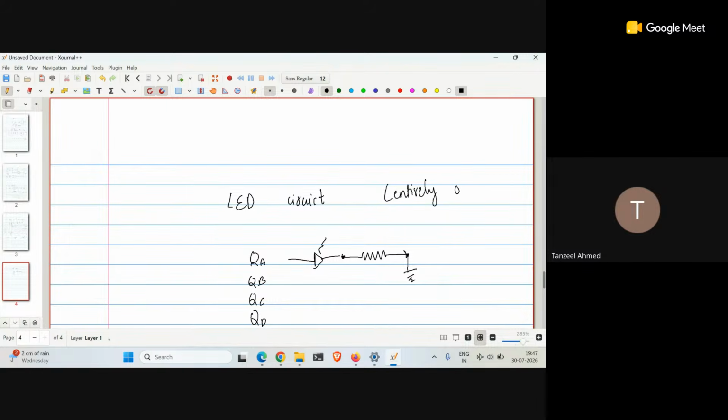To show your outputs, you can just plot the waveform that you are measuring from your oscilloscope. Plotting waveforms we have seen last time. Okay, this is showing the output by means of LED. So your LED starts glowing whenever there is a logic high because it's getting some current. But you need to be careful of the current limit of these output pins. You can only supply 400 microamperes, and the series resistor needs to be reasonably sized for that because it's a current limiting resistor. And all that you need to do, we don't want to get into right now. So this part is not really needed.